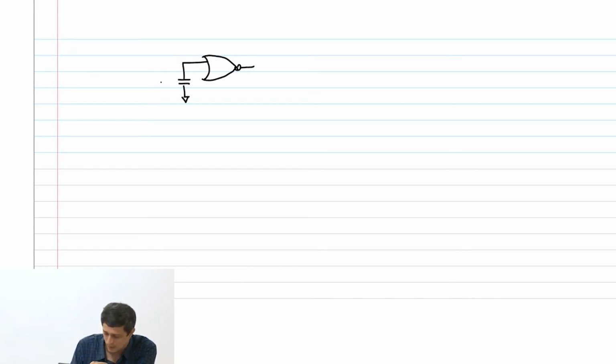So that has to be done as follows. You take the NOR 2 gate, I have a capacitance here, and we said that x2 was how much? 6, is it? Yeah, 6. So I'll first find out how much the gate has been upsized by.